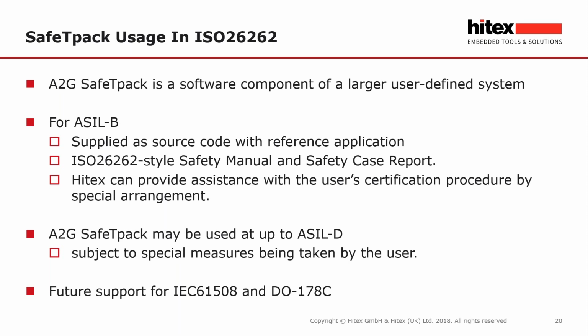You can use SafeTpack up to ASIL-D, but there are some special measures you have to take, much like you would with the MCAL, for example. And in the long term, we are intending to support the industrial standard IEC 61508 and the aerospace DO-178C and DO-254. Okay.